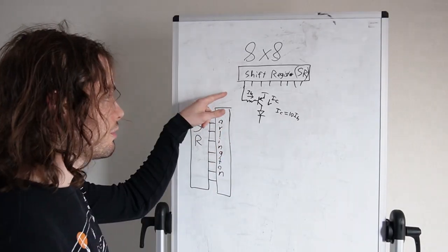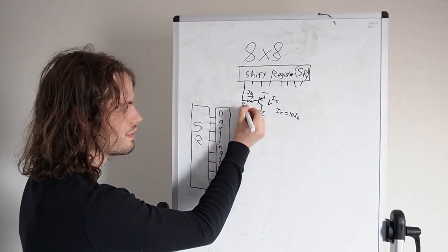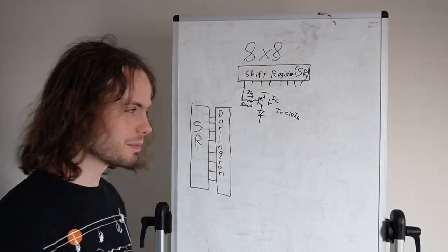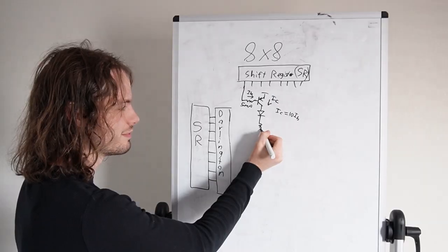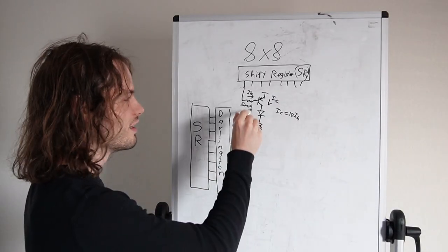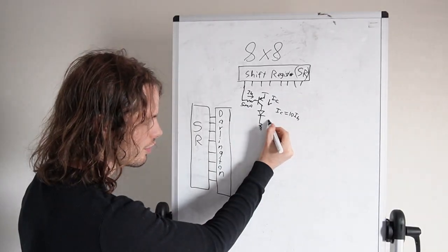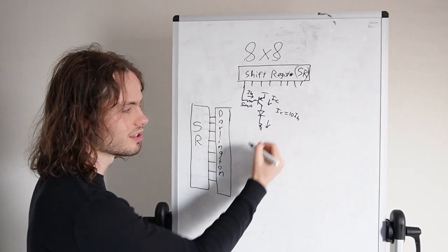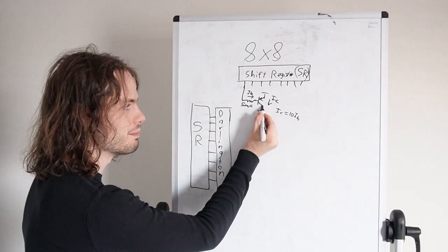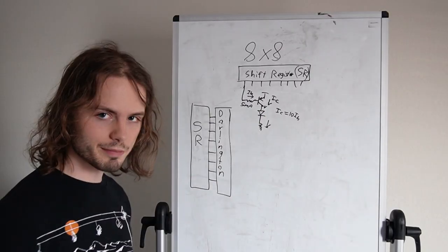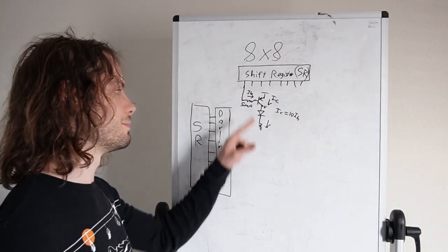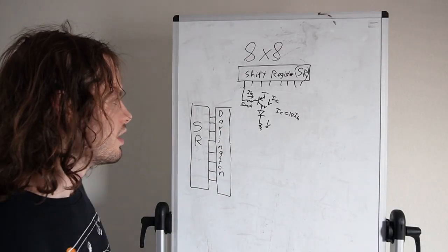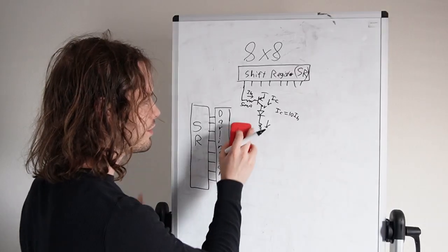So I can push with a little bit of current here, let's say even 5 milliamps, and it would push 50 milliamps. It won't get to 50 milliamps because, without getting too much into the details, there's voltage biasing here. So as more current goes through here, the voltage drop across this resistor increases, and that will push the voltage here up to a certain limit, at which point the transistor stops amplifying and it finds that equilibrium point. So that's why I'm using the BJTs.